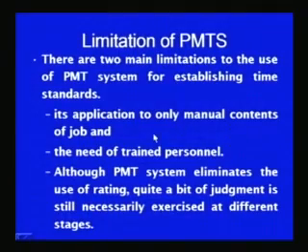But there are certain limitations also associated with the PMTS method. The PMTS method can mainly be applied for manual jobs, and it requires experts for its application, because fine breaking of the job into fundamental motions is required, and for those motions time values are obtained from the different PTS systems.